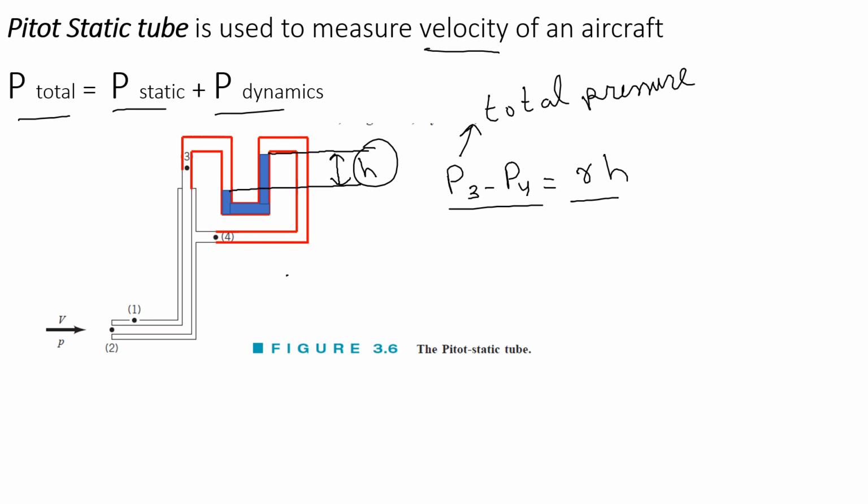As you can see, this is the total pressure because this surface, this control surface, is facing the upstream fluid. Just like in the previous slide, where we drilled a hole to see the static pressure of the fluid, this is the hole that we drilled and attached a piezometer tube, and here we again are looking at the upstream fluid.